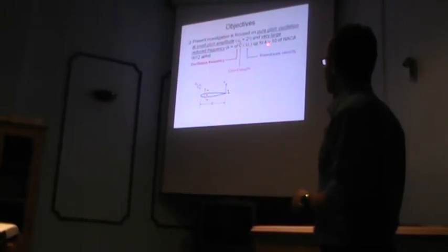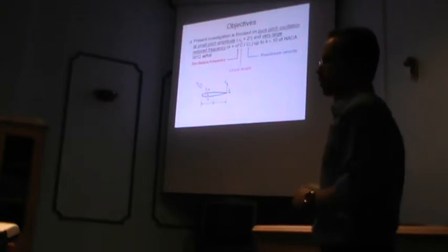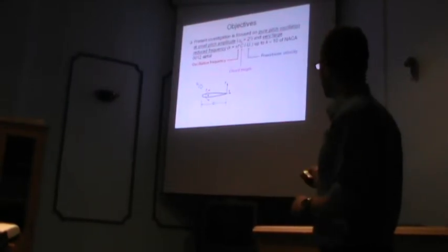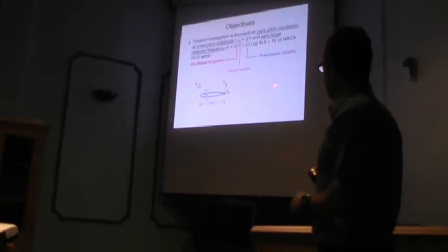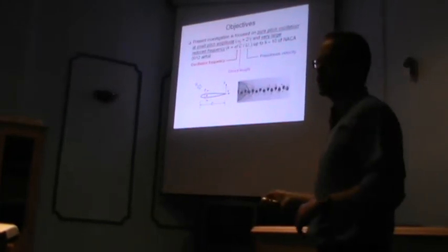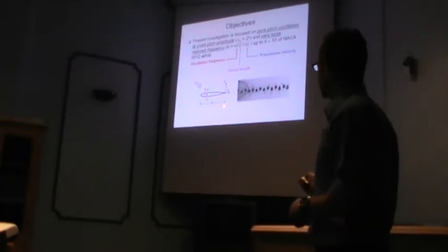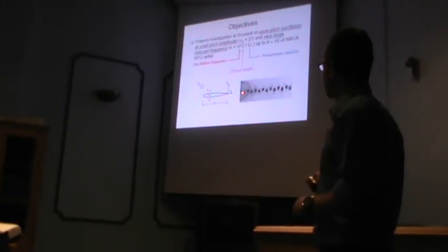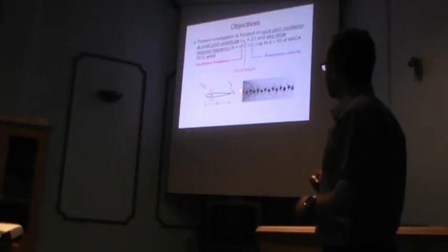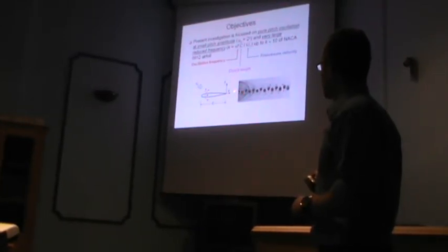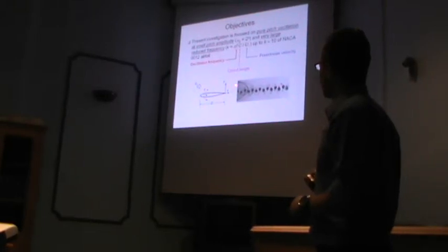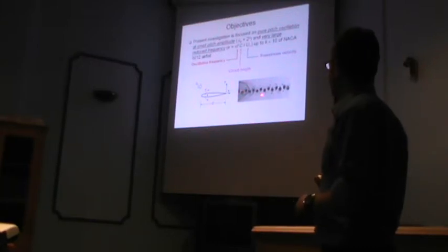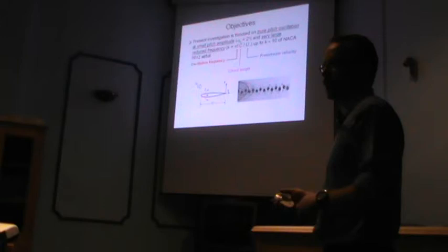And we'll go to frequencies K up to a value of 10, which is very high in this kind of application. Now, if we actually look at the wake of this airfoil using some dye flow visualization, what you will see is that as the airfoil oscillates up and down, you actually form this highly organized periodic train of counter-rotating vortices. So you can see the one on top is in the counterclockwise direction, and the one on bottom here is in the clockwise direction, and then they basically repeat in an organized fashion.